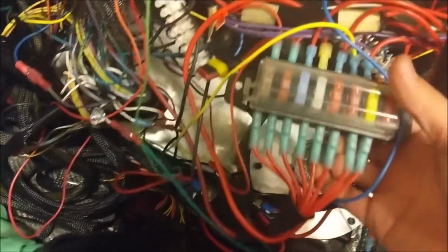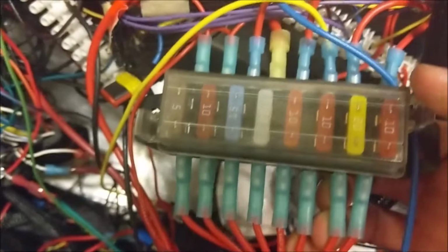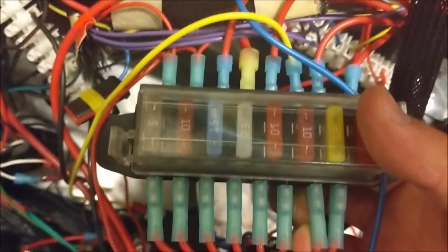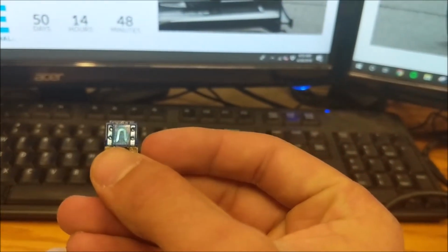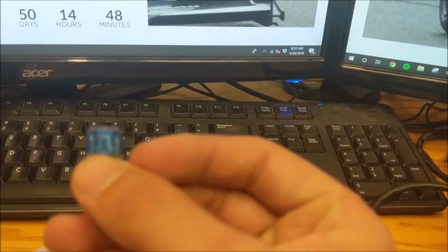The most common issue is with a fuse. Usually, a fuse blows because the amperage in the circuit reaches higher than the fuse is rated, breaking the circuit and protecting your components. Fuse failure is common, especially on the formula car. Be sure to watch out for a broken fuse. As you can see, this fuse is fully intact, but if you look real closely, you will be able to see a break in each fuse if a fuse is blown. If not, put the fuse back and continue searching.